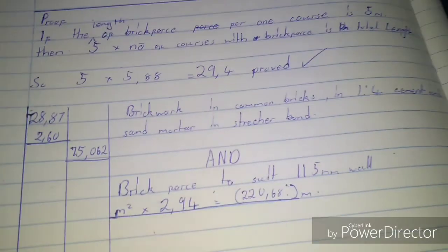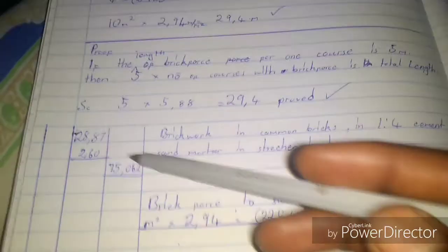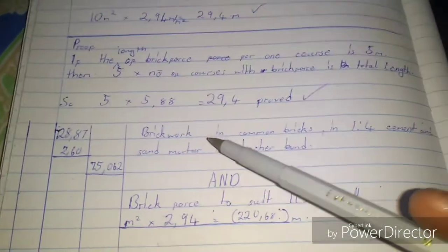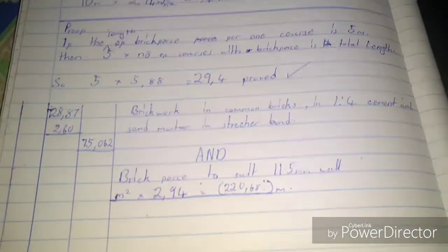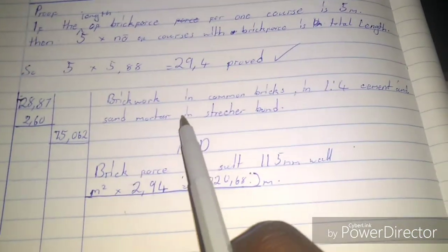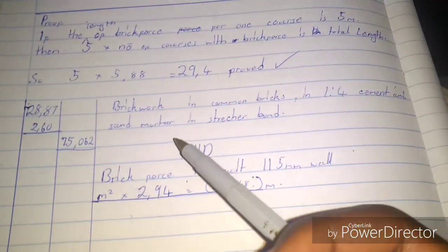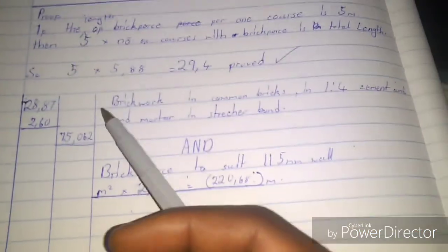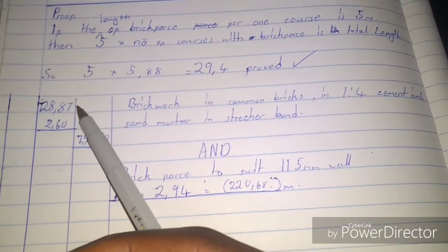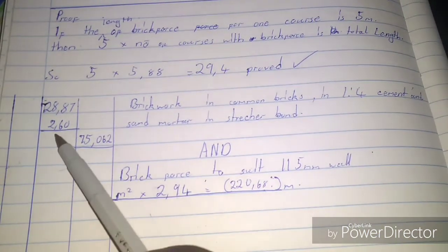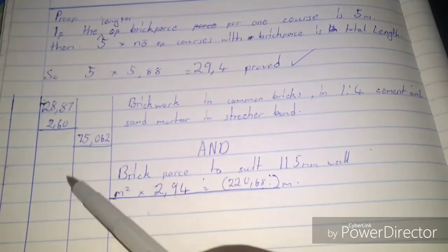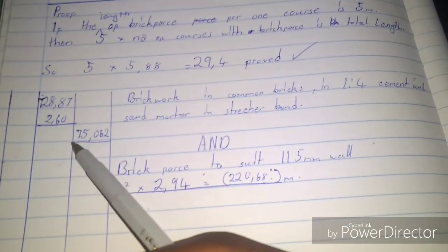So here is how you put it on your takeoff sheet. So let's say we're calculating for brickwork. So our description reads, brickwork in common bricks in 1:4 cement and mortar in stretcher bond. And then we've got those dimensions, 28,87 and 2,60. You multiply those two, you get